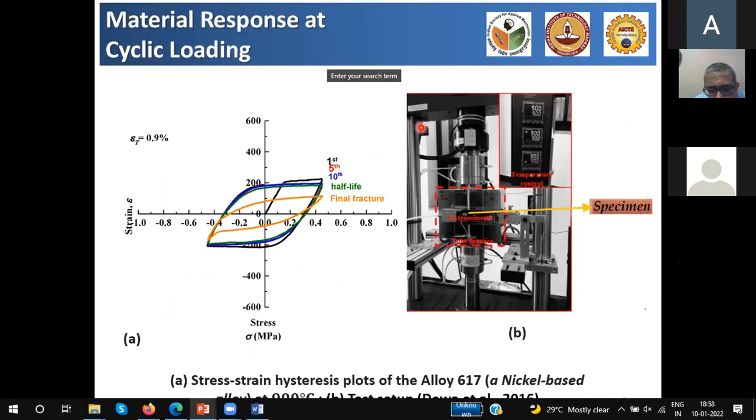So moving forward, you also have tests that need to be done in cyclic loading. Again, in the olden times, people were simply monitoring the number of cycles to failure and developing something called a Wöhler curve, which served some purpose to find out how many cycles your material can withstand, and so on. And when you have a combination of these cycles, people were just combining what they defined as a damage under various loadings, and then tried to predict the life of a structure.